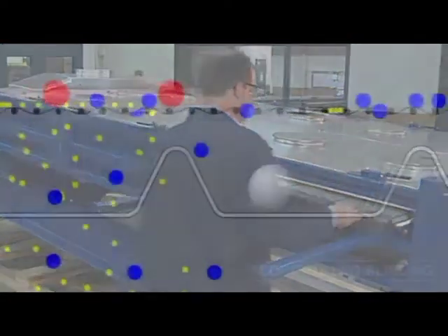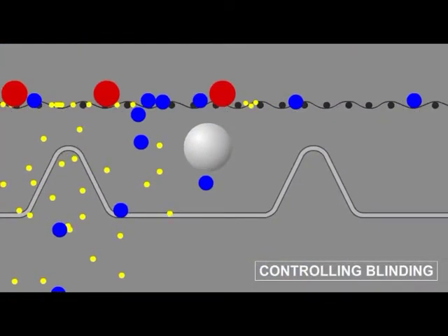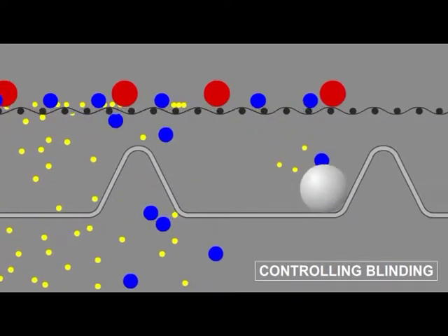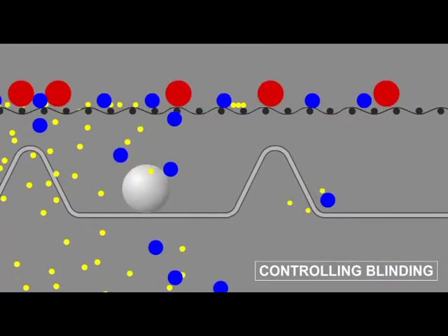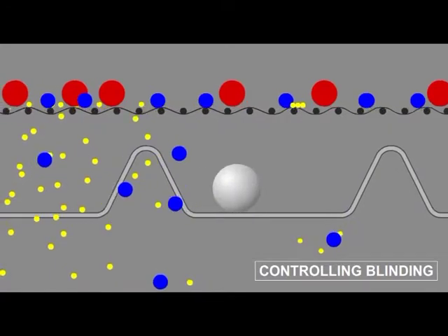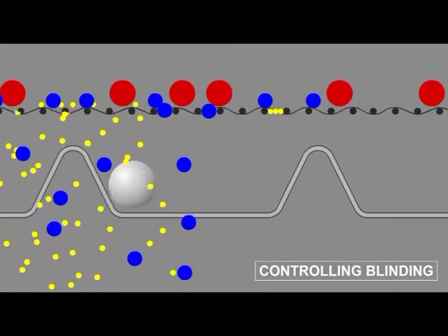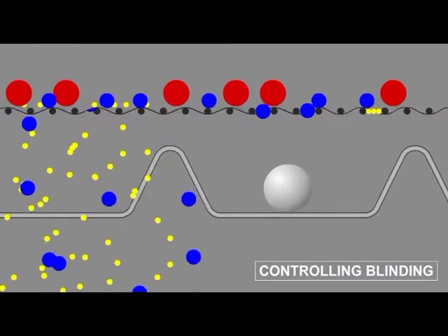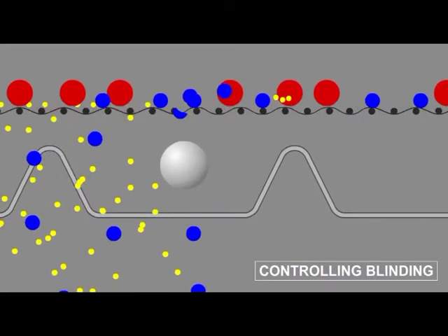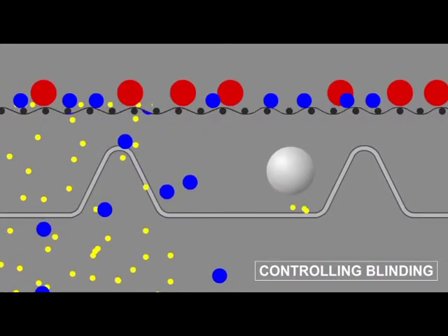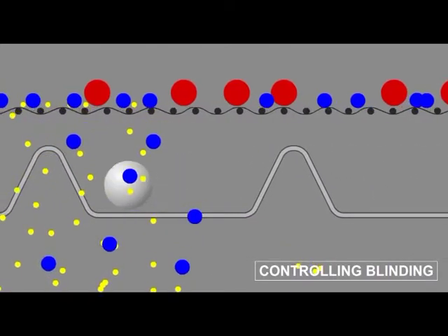The long-stroke gyratory reciprocating motion drives the mesh cleaning balls into the underside of the screen, cleaning out the material. Shorter stroke gyratory and most all vibrating screens provide less force and are therefore less effective at mesh cleaning. A long stroke gyratory reciprocating motion will keep a screener operating longer than other mesh cleaning systems, minimizing unplanned downtime.